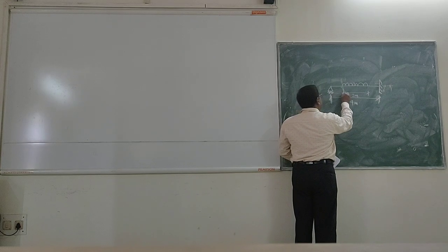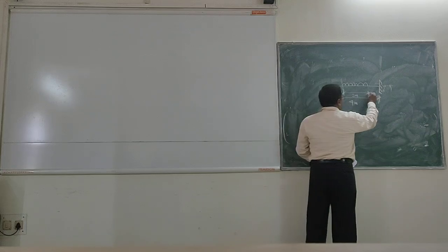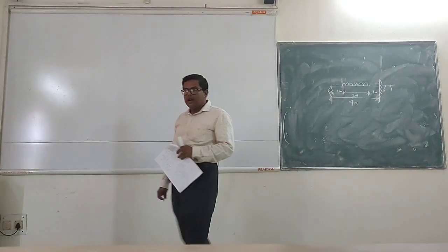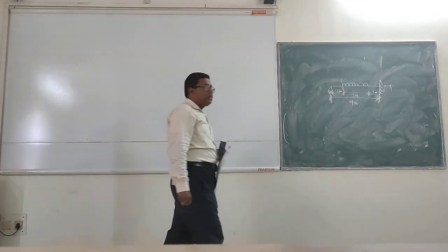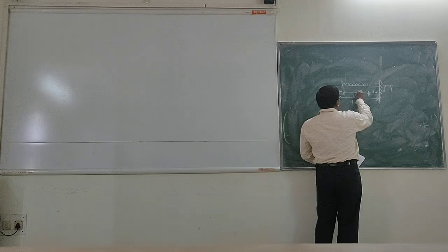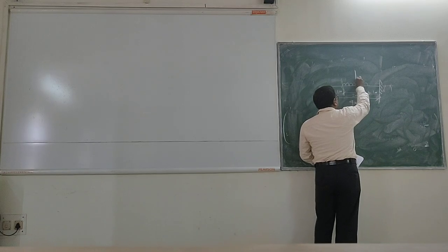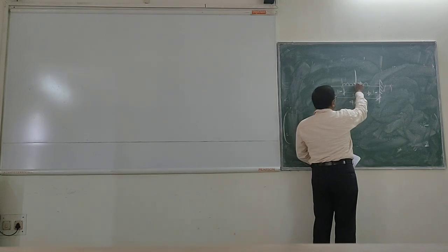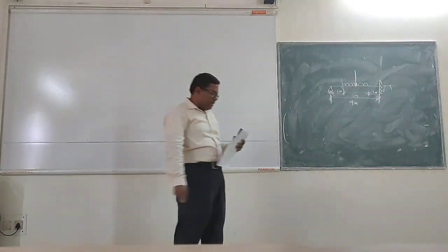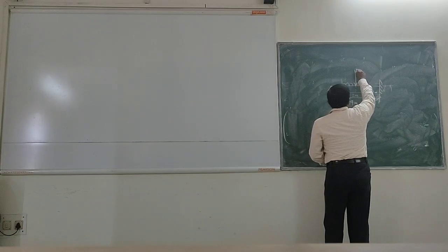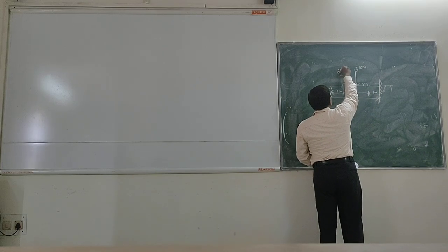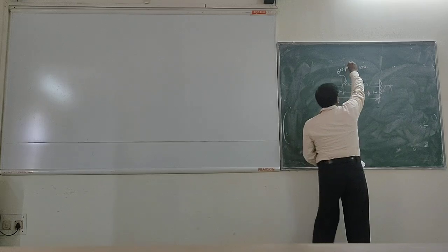This distance is 1 meter, and this distance will be 1 meter, right? Correct or not? Is it clear? Along with this uniformly distributed load, at the middle of the beam, so at 2 meter from this end, there is a concentrated load also acting on the beam. Let's say that load is 5 kilonewton, and the UDL acting is 6 kilonewton per meter.